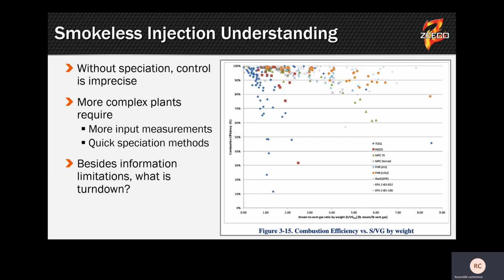When we're flaring, we're so interested in making sure that we have good combustion efficiency, that we have a good flame quality. And for the most part, the industry has taken a very indirect or proxy method to that. The tried and true vast majority of operators are using ratio control, whether it's steam or air injection. What that means is they measure the flow rate for a flare flow, and then inject some proportion of steam or air. And that's led to quite a bit of insufficient combustion efficiency and poor operations.